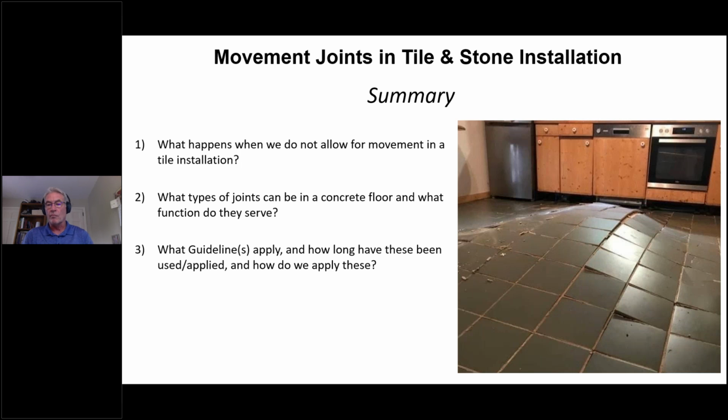But if it's new concrete, I'd be concerned that it's going to continue to shrink as it cures, and you're going to have a different profile once your tile is set and it dries out. So I think there could be potential problems with that, definitely. Minor ones that have been there 20 years, I'd do it in a heartbeat. But if they're new slabs, that's a whole different animal. And I think a structural engineer has to address that, or the design professional.